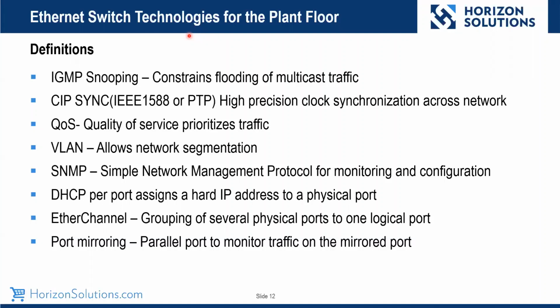Another thing that drives have, which is pretty cool to complement that, is auto device configuration. So our drives, we can configure those. So not only push the IP address down, we could push the configuration down and the firmware. So just by taking a drive, plugging it in, wiring it in, we could configure that drive and get it up and running without any intervention.